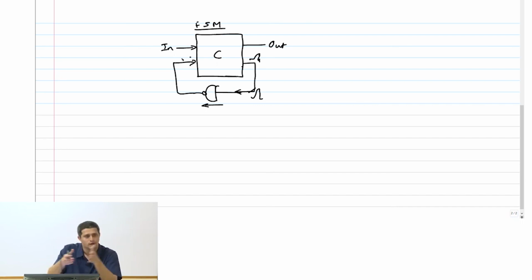Of course, you have to give enough delay. You can't give like 30 picoseconds and expect things to work, right? You have to give enough delay so that you can do something with it. Okay? So, in order to get a delay which we can control, we put a sequential element here in between, and that's a flop or a latch, and this will be controlled by a clock.